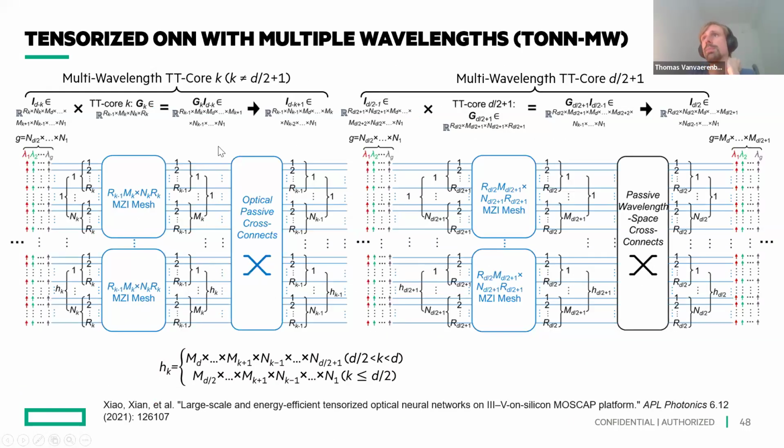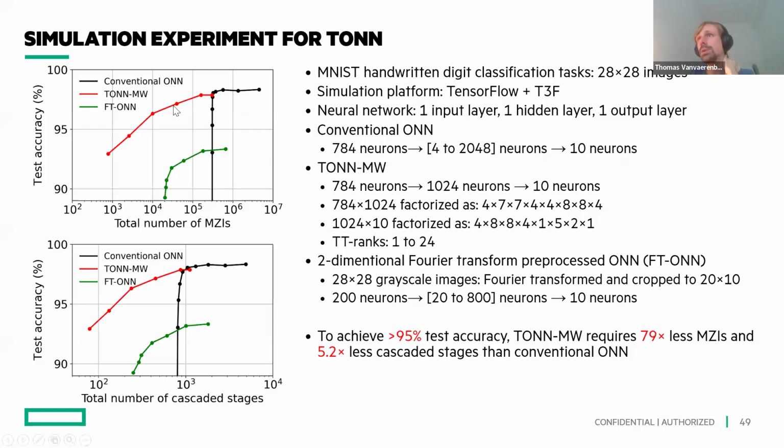What is happening is, if you map this thing to hardware, you get a couple of crossbars, which are native crossbars that I've been talking about before, nothing special there. And so indeed there's a size limit there. That is a constraint. But when we have our use case, we have a matrix that we want to deploy to our hardware, we need to follow an existing decomposition method that transforms our desired matrix into something else. And this type of test is actually really going to tell us whether, with the constraints of the hardware, we will get a big penalty hit for the test accuracy or not. And that is a study that I don't think we've done.